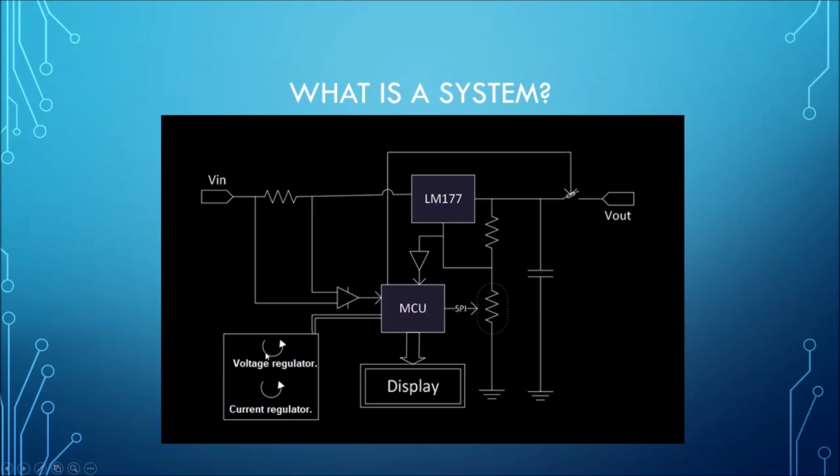This can be done using electric potentiometers or some type of adjustable dial that generates pulses. Display allows the user to calibrate and view the voltage and current parameters in real time. Sense resistor and amplifier. A resistor, together with an amplifier, is used to measure the current flowing to the load. Protection relay allows the load to be quickly disconnected from the source in the event of overcurrent or overvoltage.